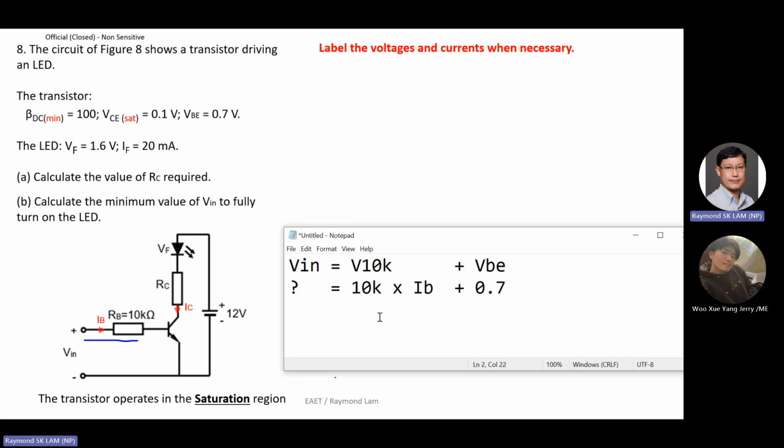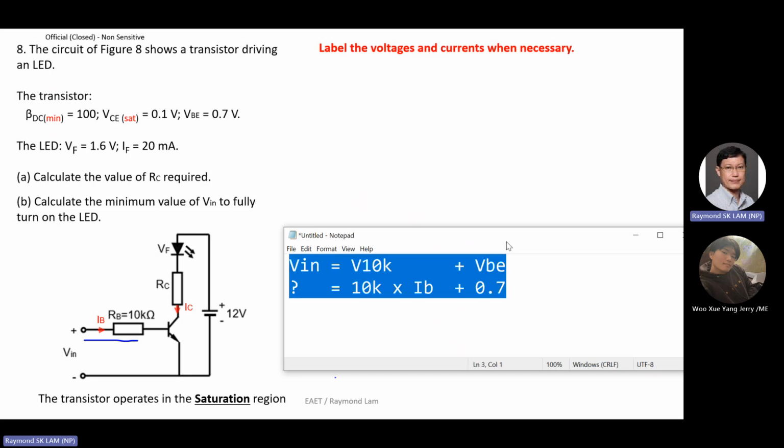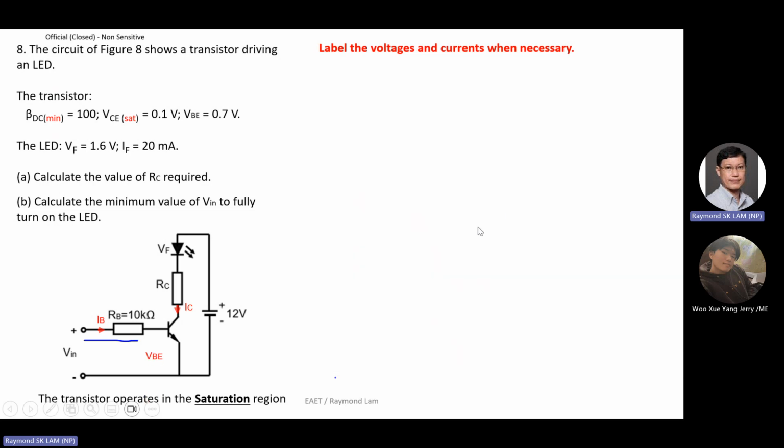That's why I say, although we have 3 steps, sometimes this is not step 1. This one maybe step 3. So if in this step you cannot solve the equation, then you should do the other loop, right? You have to try and error. Even myself, I also don't know, I have to try first. So now I will do the loop at the collector emitter junction.